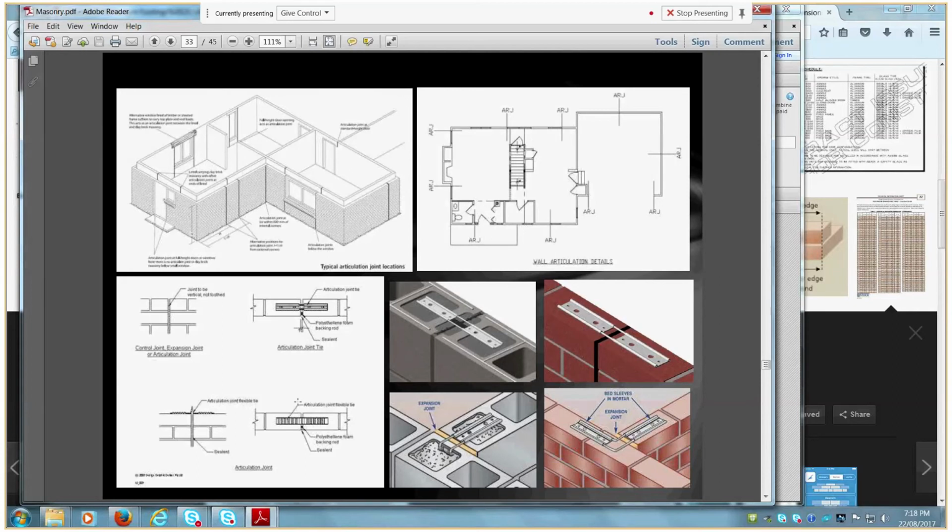That's my experience, that engineers generally do the control joints, because they've got all the information. They know the soil type, they design the footings to accommodate it, and then they put the control joints in accordance with the plans and the soil. It then becomes one package, and you can always relate that back into your plans.